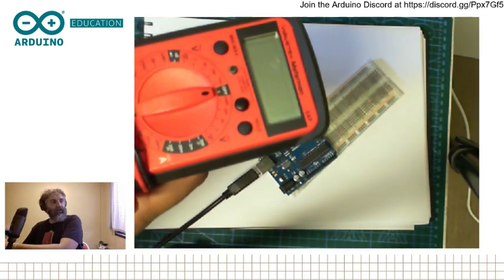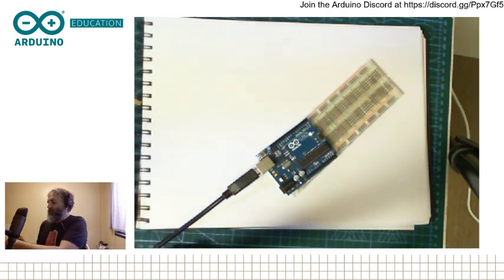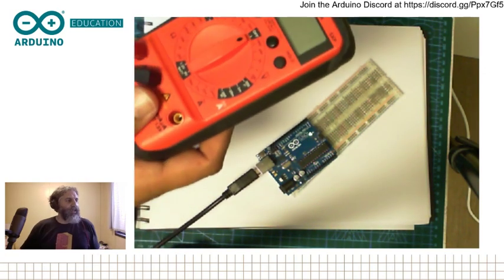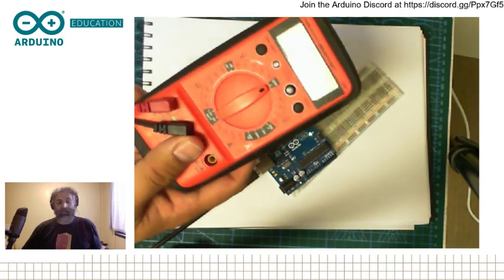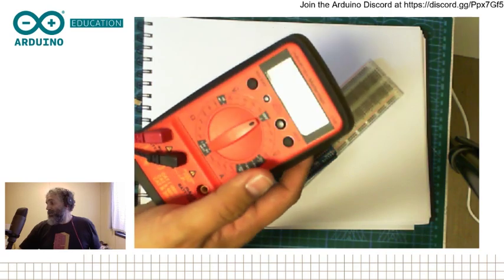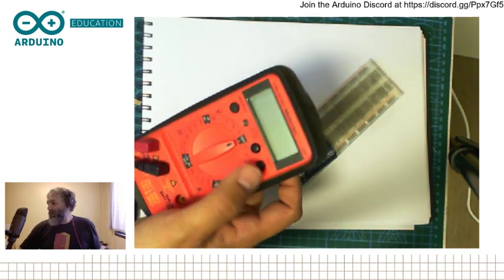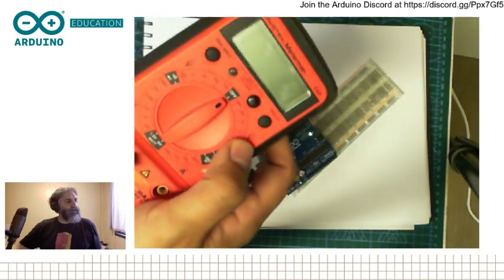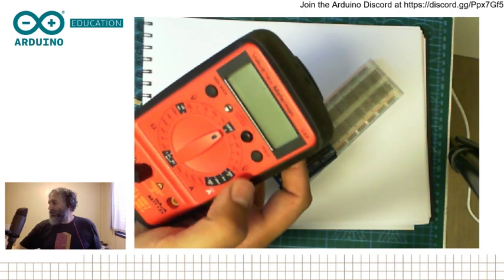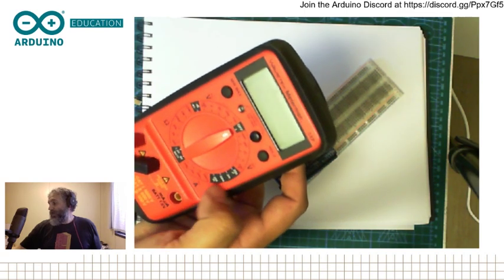So this is the multimeter here. You see that there are different types of multimeters. The more expensive ones are completely automated. This one is mid to mid-high range. It's pretty good. It has different areas of measurement around it. It has an area that measures direct current voltage. You can also measure direct current. This is the A with the double line on top.